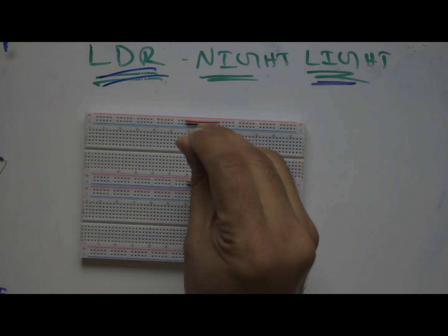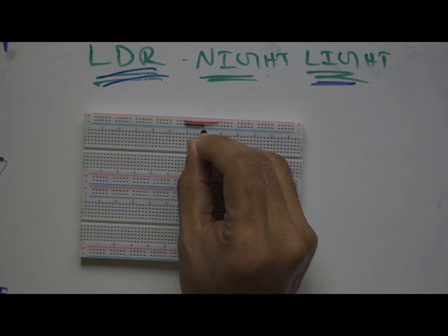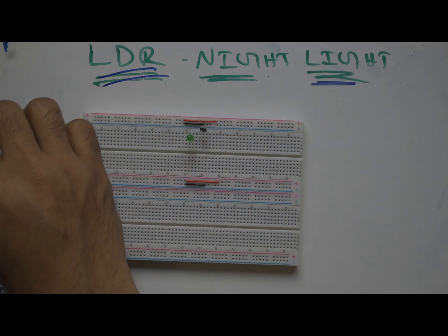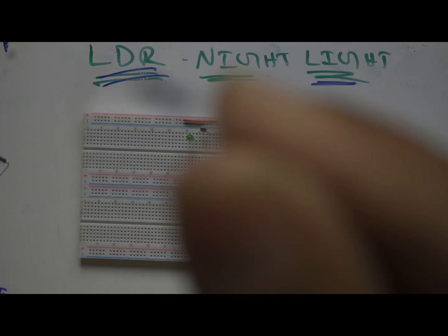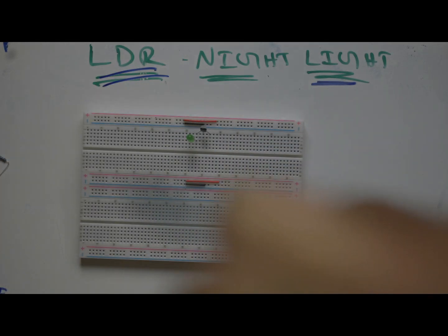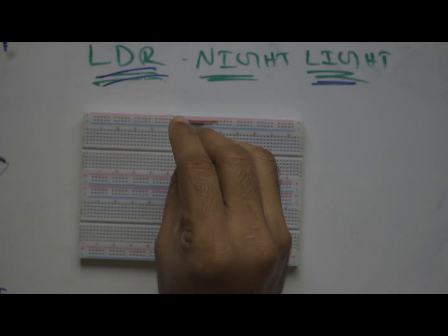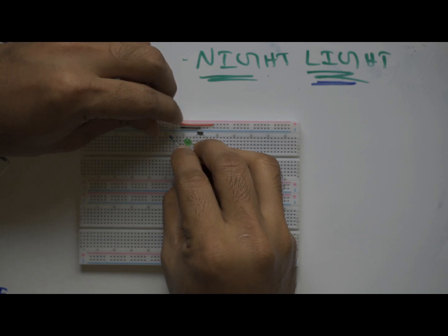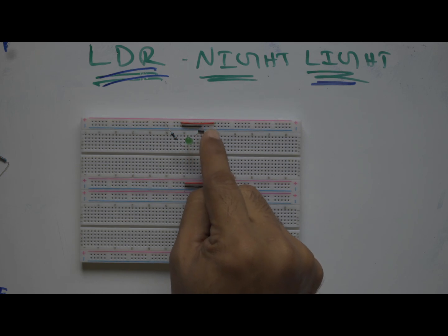And let's hook up this LED here. So this is just to drive a simple circuitry, and if you want to drive a bigger circuitry, you guys need to have a relay. And this is a 390 ohm resistor. Yeah, it's a 390 ohm resistor. And then just hook this up. So the 390 ohm resistor comes to the LED and then goes to the base of this transistor.